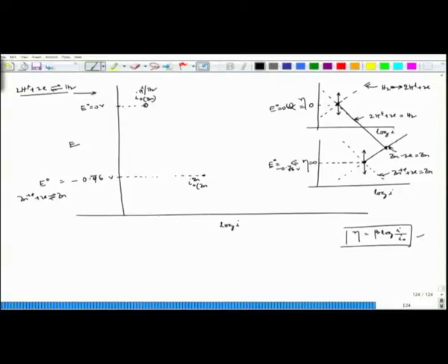Once they meet, you see that the potential is E corr, which is in between these two, and for that you can see that polarization for zinc is on the positive side and polarization for hydrogen is on the negative side. So, hydrogen is cathodically polarized and zinc is anodically polarized in order to achieve this mixed potential.